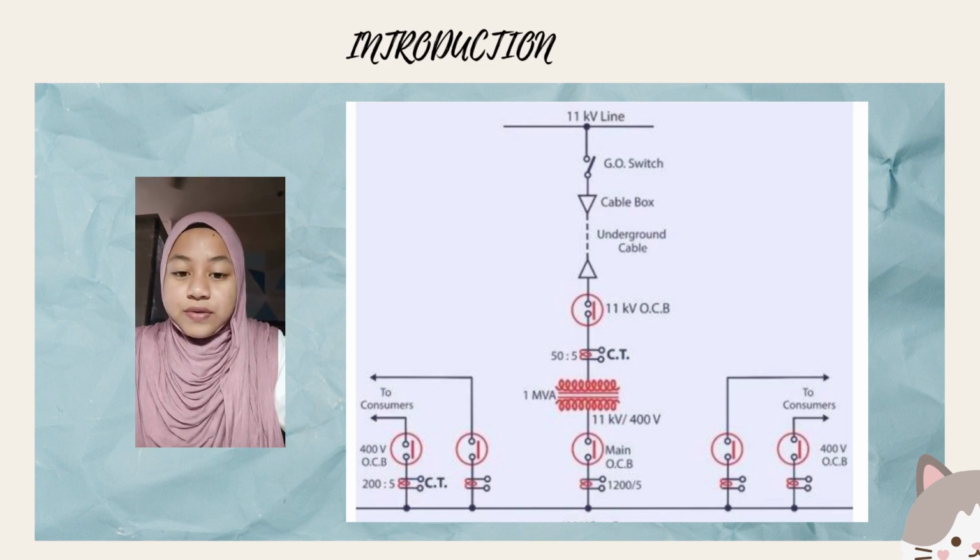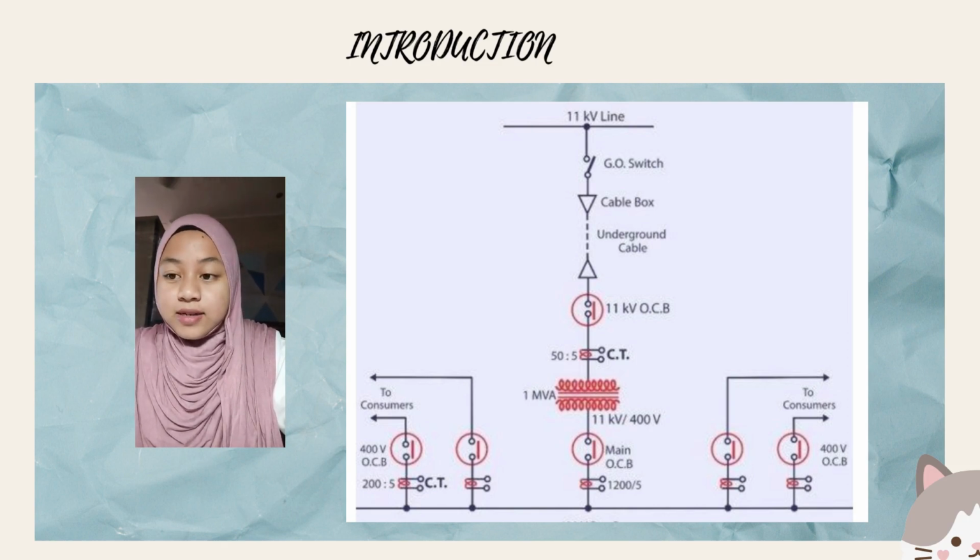A single line diagram is a three-phase power system that is symbolically and/or graphically represented by a single line, also referred to as a one-line diagram. It is a diagrammatic representation of all the connections and equipment. In a single line diagram, only one conductor is shown using a single line, as opposed to each of the three phases being represented by its own line.